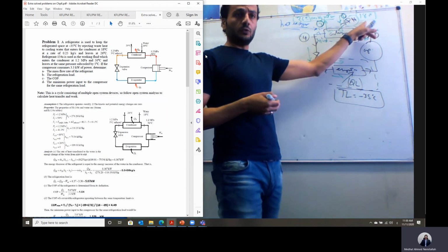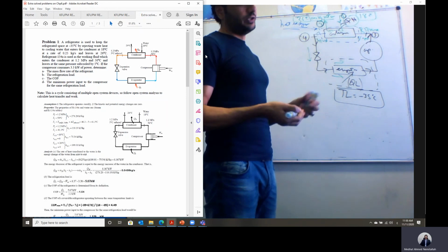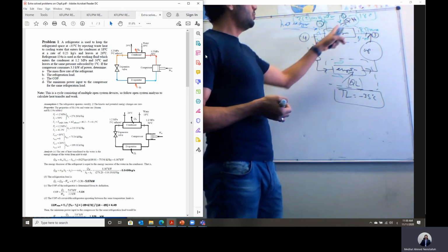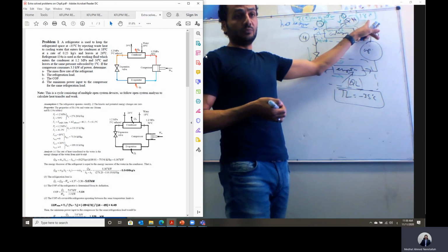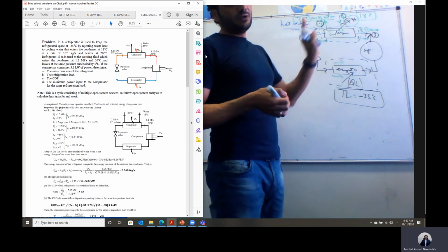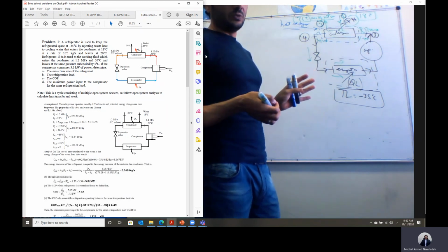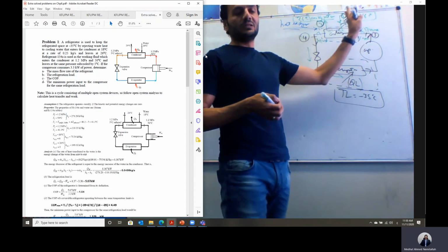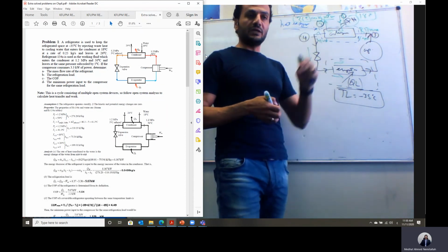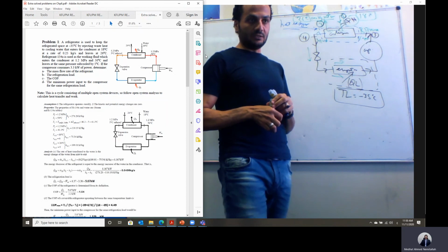For subcooled liquid at low pressure we don't have a subcooled table, so we assume that the enthalpy equals h_f at the given temperature from table A4. Or we can consider it a liquid incompressible substance, so delta h equals c_p multiplied by delta T, and c_p we can get from table A3.